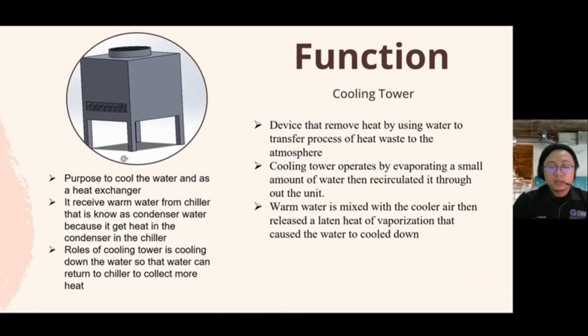Okay, our second device is the cooling tower. The main purpose is to cool the water and act as a heat exchanger. It also receives warm water from the chiller, now called condenser water because it got heat in the condenser of the chiller. The role of the cooling tower is cooling down the water so that the water can return to the chiller to collect more heat.